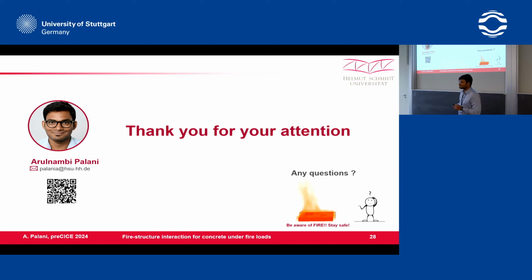Thank you. Just a question, do you take into account the conductivity of the solid at all in terms of thermals? Because I noticed the two-way coupling is more like damage back to the fluid solver, but I could imagine that you also have thermal conductivity along the wall as your temperature dissipates through. And as the water is being pushed in and out, that would also probably change the thermal conductivity of the wall. Yes, that is true, I can see a number of challenges there. As I said, these are preliminary results, but we also look at the thermal conductivity.